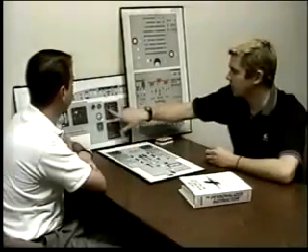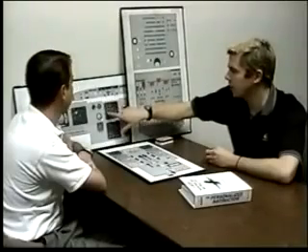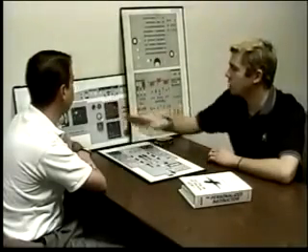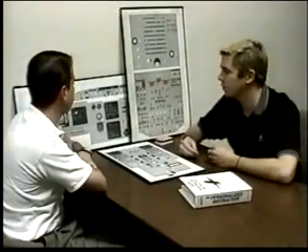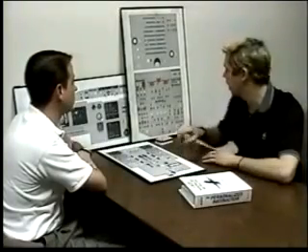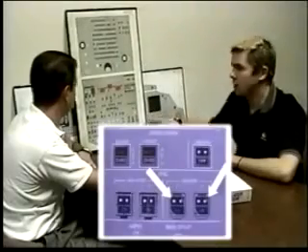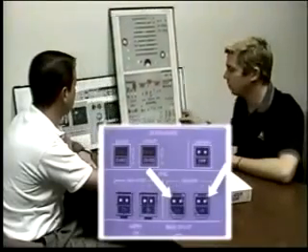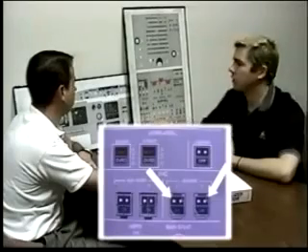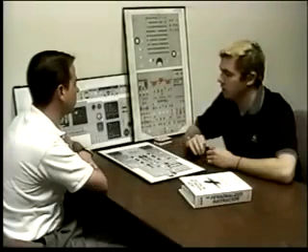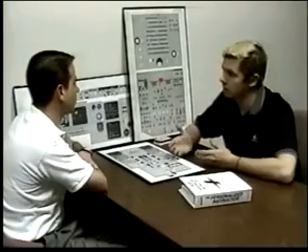And there are various indications down here that are going to tell us where the TLAs are and such. If one engine falls out of EPR mode and goes into either N1 rated or unrated mode, I need to select both of these switches to on. I need to force them both into N1 mode. If I'm forcing an engine into N1 mode, I can only force it to an N1 rated mode. To get to an unrated mode, it has to degrade.